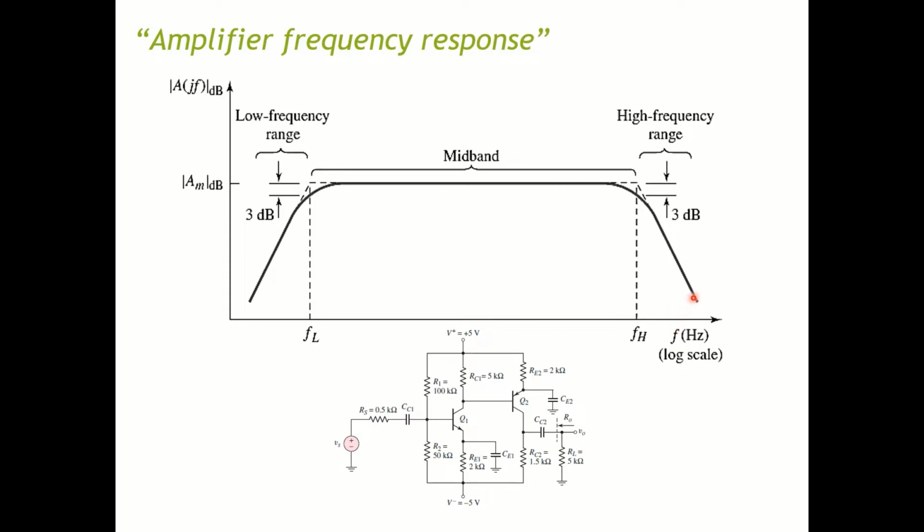That is because when your frequency is high enough, those internal capacitors no longer act as open circuits. They start acting like short circuits and reducing your gain.